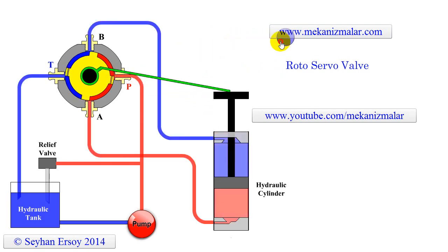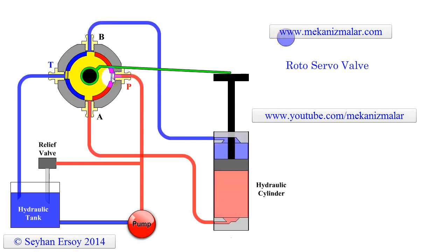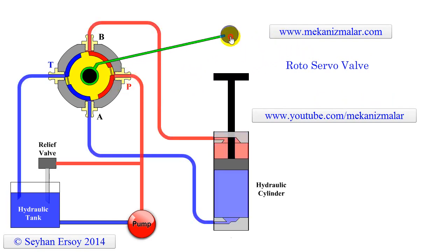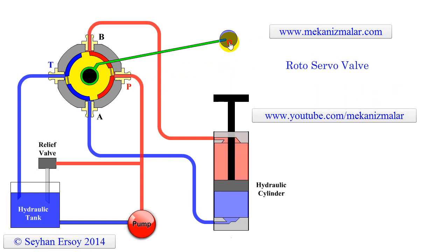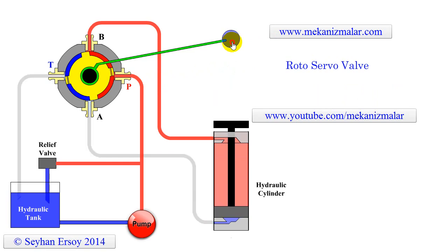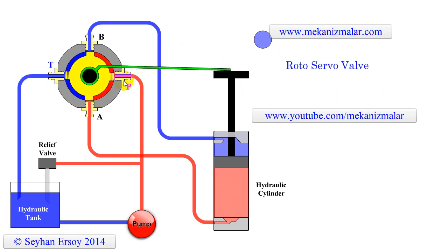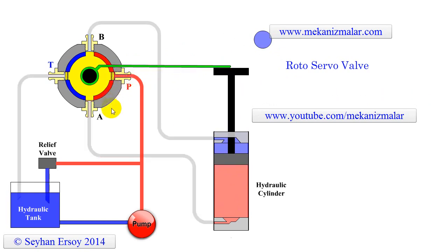This causes the amount of oil supplied to port A to decrease. In turn, the extension of the rod slows down. The piston rod stops advancing when the green arm comes to horizontal level, which is the equilibrium state. If there are any parts on the platform, the piston rod would stop when the top part of the green arm comes to the horizontal position.